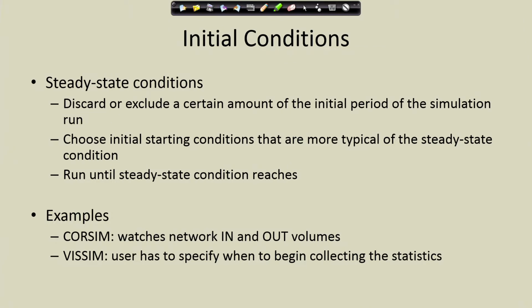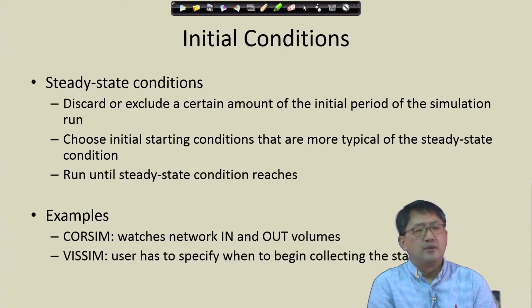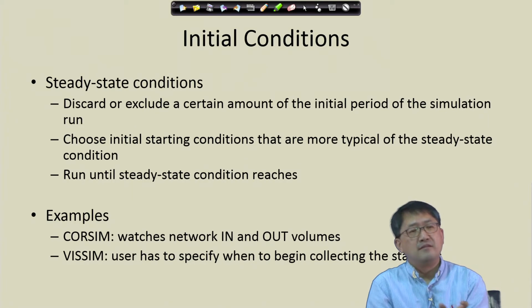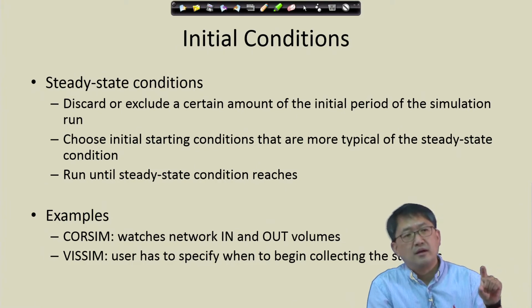And this is a function of variability and the number of runs you make. Maybe we'll talk about it in more detail later. And another aspect is that if you are doing delay at the intersection level, one easy argument is that I'm going to consider the level of service A range as similar. Level of service A is up to 10 seconds per vehicle. So if you have a 2-second delay versus a 9-second delay, even though it's a 7-second difference, it's still a good A level. That's some justification you can use.